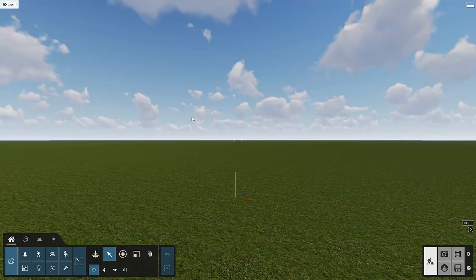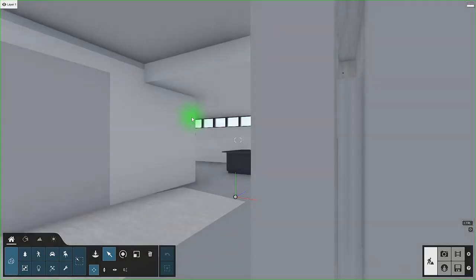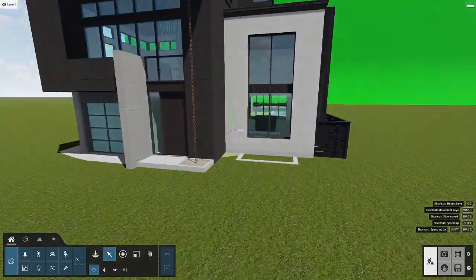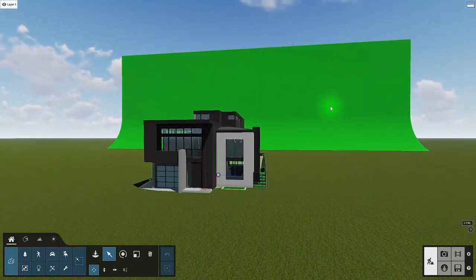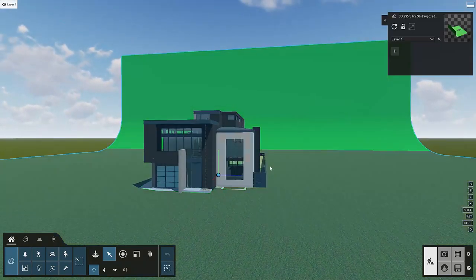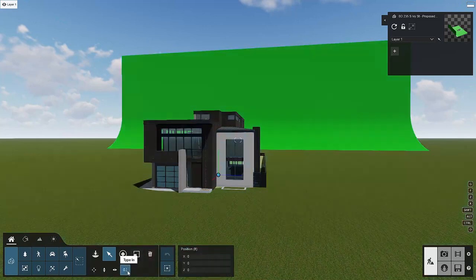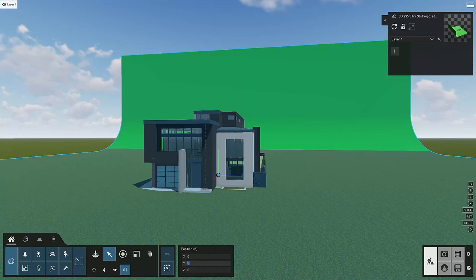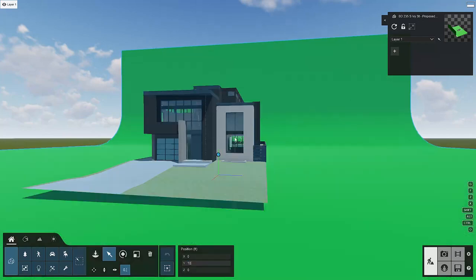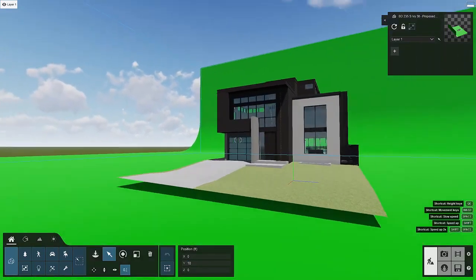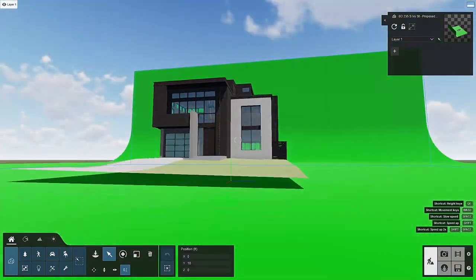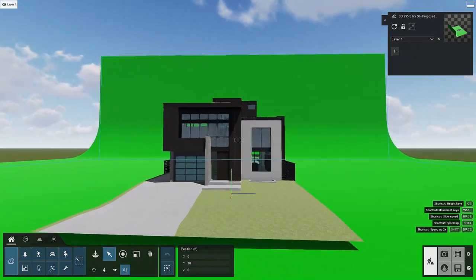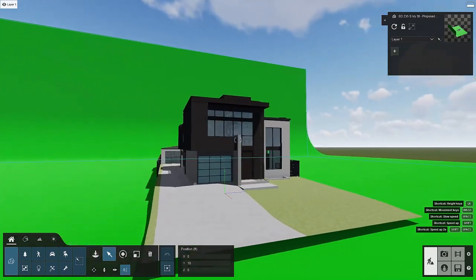All right, so now SketchUp and Lumion LiveSync is doing its thing, and our file lands here over into Lumion. Everything looks good. Now, I'm going to select that model, and then what I like to do is click on the Type In field down here, and on the Y dimension, I'm going to make that a 10, so that our model sits 10 feet up above that Lumion ground plane. You can see what's going on there. Looks good enough, all right? And I just like to insert my models at a known point.